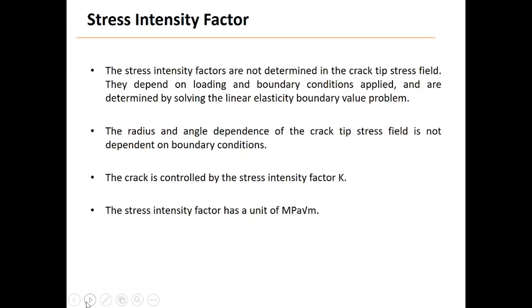Now, just summarizing what I said about the properties of the stress intensity factor. When we got the crack tip stress field solution, the factors are not determined. The solutions are all determined, except that factor. Because we apply different loadings, that factor can change corresponding to the boundary conditions, but the stress field itself and the displacement field itself are universal. It doesn't matter what sort of crack geometry you have.